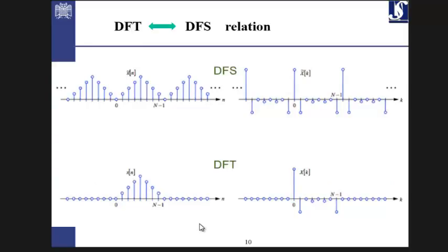In a simple form, shown graphically, if you want to see how it's implemented, the signal is limited in time for the reasons I told you already. The signal is assumed to be limited in time when we want a DFT which is reversible without losing information. What taking the DFT actually means is that you continue this signal and make it periodic using the period of N, which is the resolution of sampling.